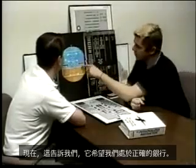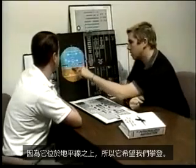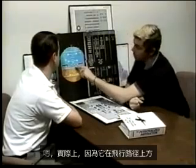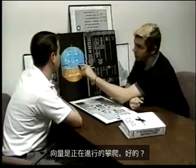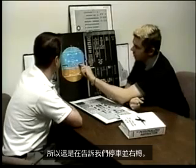Right now, this is telling us that it wants us to be in a right bank, and because it's above the horizon line, it wants us to climb. Well, actually, because it's above, the flight path vector is the climb that's going on. Okay, so this is telling us to pull up and turn right.